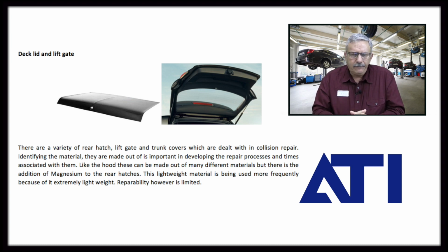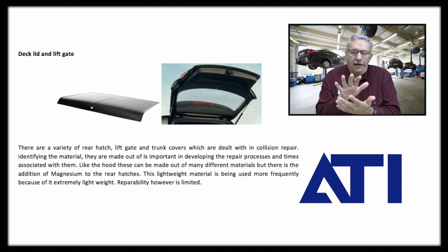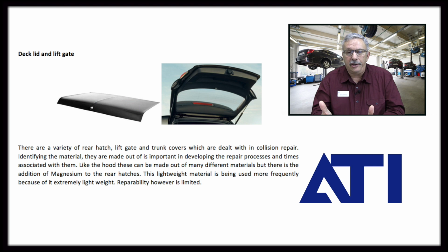But a couple of things with these lift gates that you'll see. We've got to be very careful now because these are another part that we're using either composites as a structure or magnesium as a structure with aluminum on the outer skin, sometimes high-strength steel on the outer skin. Why does that make a difference? Well, it's a huge difference when you're working on a part that has a magnesium frame. There are some very specific repair parameters. Actually, there's not a whole lot of repair you can do.